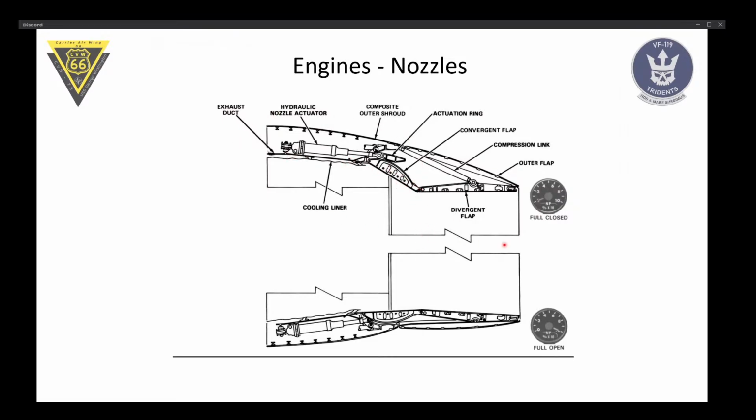By the way, the upper part is the nozzle in the closed position, and the lower part is the nozzle in the open position. But let's first focus on the closed position. This is the position you're going to have in flight whenever you're not using afterburner. So air is coming here. So here's our afterburning chamber. We're getting gases. They're getting deflected and constricted, which means they have to accelerate, and then they accelerate out and maximize our outflow velocity and thus maximize our thrust.